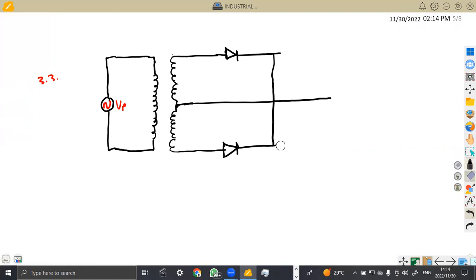And that's where we are going to have this capacitor. Remember, they need us to have a capacitor and the resistor, which is the smoothing circuit. So this is now a smoothing circuit that you're going to have. So that's what we needed here. Like I said, this is our D1, our D2, then we've got our center tap here.